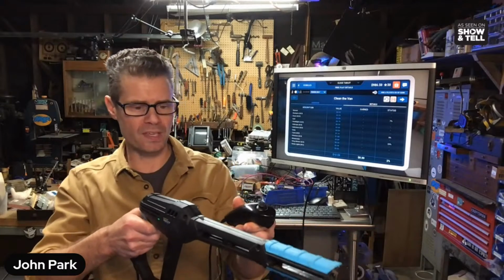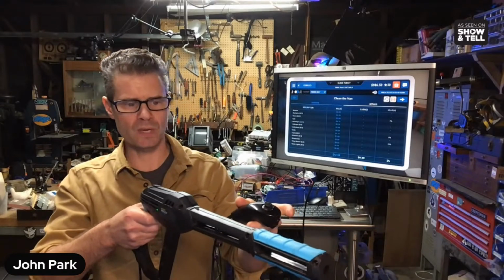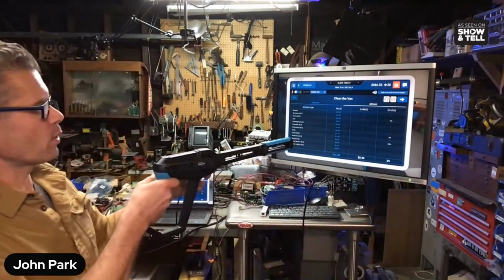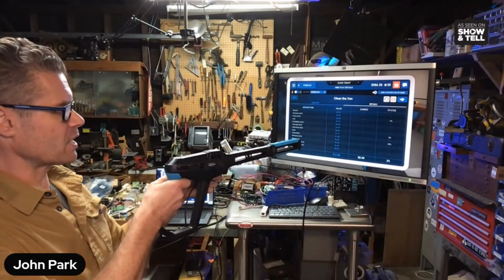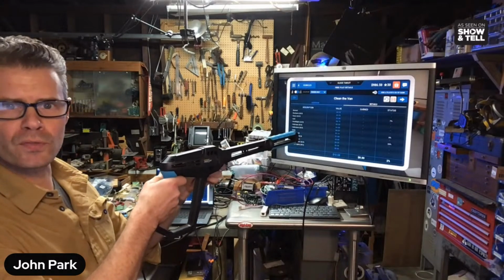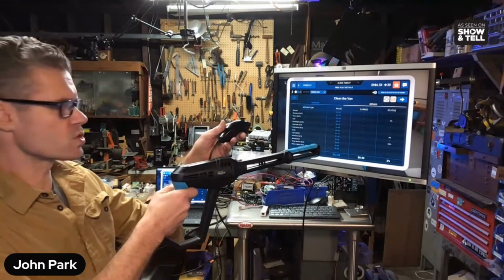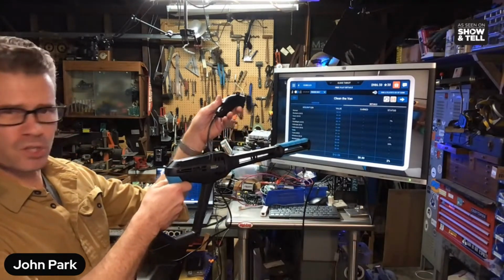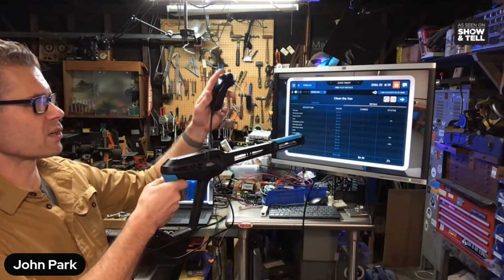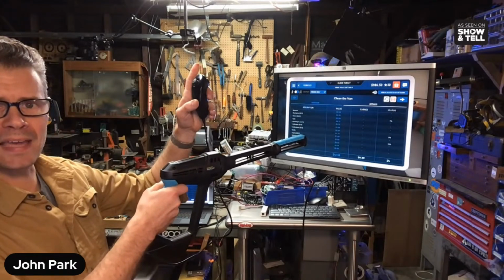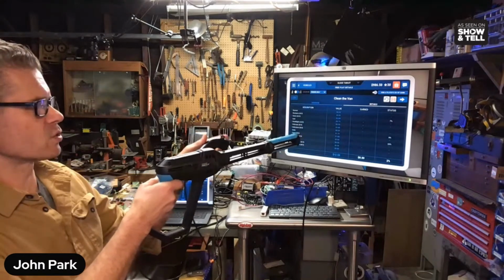And one of the things that I've been working on that's new with this is we need a way to set relative offsets. If I'm going to play the game pointed at that screen there, I need to let it know that that's center, and so don't move the cursor until I move it off of center. And so that's how I'm using one of the functions on the WiiChuck, which also has its own little accelerometer. When I tilt up, it says, okay, you're tilted up. And now when I press the C button, that is resetting my offsets to the position that I'm at.